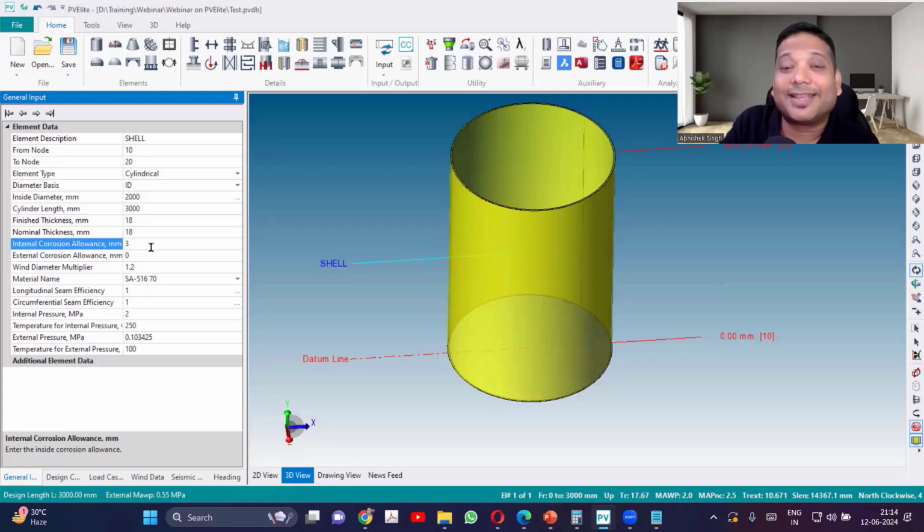Mill under tolerance. If you're procuring an 18 mm plate, you'll be getting, see, the plate manufacturer also needs tolerance, right? 18 mm does not mean anything in the physical world. We need tolerance to make anything, right? So it'll be under tolerance, like 0.3 mm under tolerance for plate. That is the permissible limit. Plus, you can go up to, based on the thicknesses, plus 2 mm also.